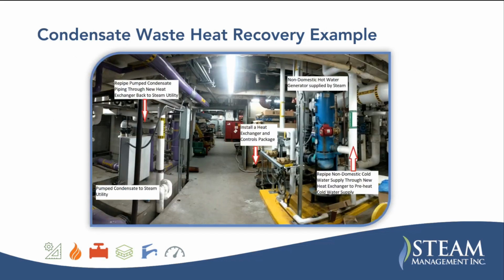So this is a real example. This is the hospital that we're at. This is the collection tank here. This is the hot water heater. We want to take condensate out of this tank, run it through a heat exchanger, and preheat the water going into the hot water heater. This is a steam-driven hot water heater, by the way. So every bit of heat that we raise the non-domestic cold water, that is less steam that's required in that hot water heater to heat the water. So that's the energy savings.